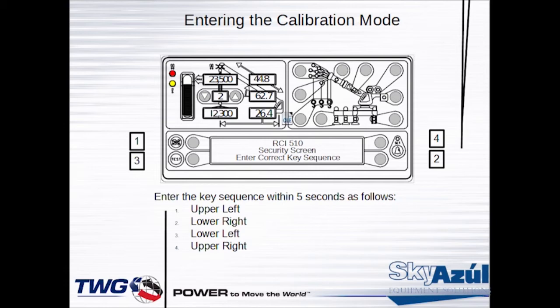Also, in this error code screen, notice here, it has the duty file number. This is a D510-300, which to me says, okay, this is an RT230. So I know what I'm working on. That's the kind of information I may be asking you for. This serial number is the serial number of the computer that was burnt in during the calibration. We didn't ask for that on the older machines as much as we do the newer ones, because we track this stuff very closely by serial numbers today. So we are getting more and more demanding about asking for serial numbers of the computers, so we can go back and pull records on them while we're working with you. So the duty file and the serial number are important. Any error codes you have are important, because we can quickly spot a sequence of events here and help you set up a reasonable troubleshooting scenario.